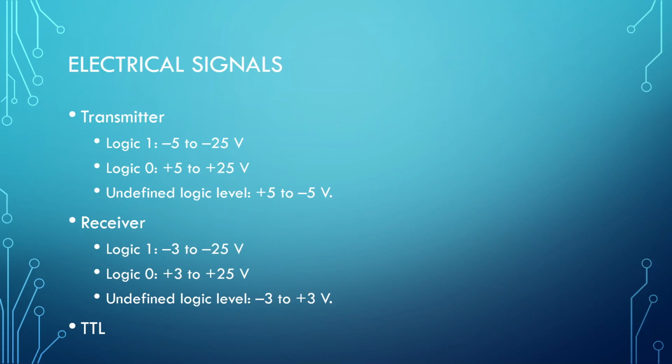The other thing that is really interesting to me, let me draw this one on the screen. You're sending these signals and they look like this. Imagine those lines being perfectly vertical, because I can't draw that accurately with a mouse. However, what they truly are is something more like this. There's more of a slant happening. It's not this perfect vertical transition.